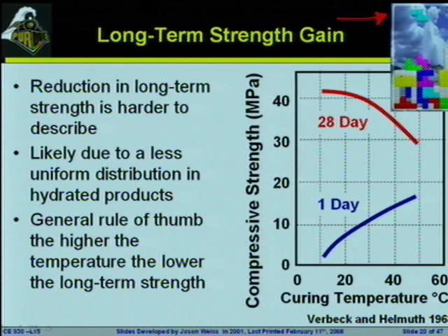When you get up to level 17 and these things are just shooting down from the top very, very quickly, you don't have enough time to make the system as dense as it possibly is, and you start seeing some of these holes inside of the system, and that variability is porosity, and that porosity can control the long-term strength.